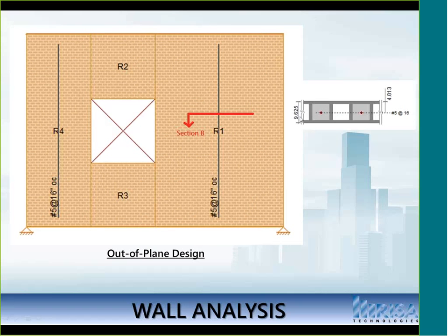So in the case of this wall, we have a nominal 10-inch thick wall, and as you can see from the cross-section here, the way we're resisting that out-of-plane bending is by placing rebar centered, so you can think of this as a beam with a depth of 4.8 inches here. And we grout and space the bars in the wall together at a close enough spacing so that there's enough moment capacity out of plane to handle those forces.